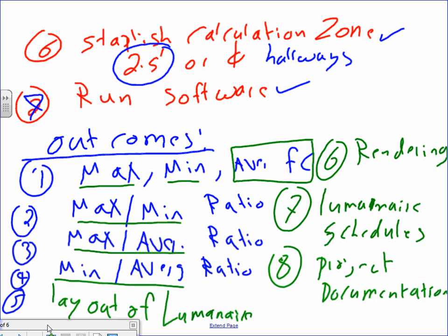And when you imported it into Revit, what did we do next? You drop the actual physical fixtures, 3Ds and intelligent devices into Revit, exactly where they should be. And then what did we do? We tag them with the fixture type, the switch that's going to switch them, and the circuit that's going to power them. Right? That's what you did. So you circuit them, and you switch them, and you tag them. And that's exactly what the whole chapter 16 talks about.